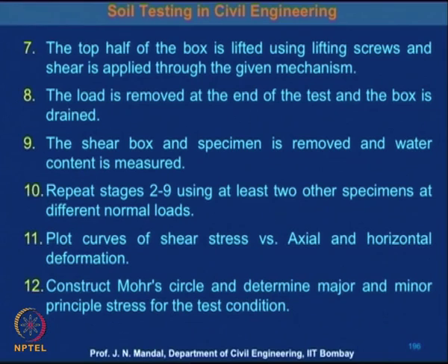Then plot the curve of shear stress versus axial or horizontal deformation. Then construct the Mohr circle and determine the major and minor principal stress.